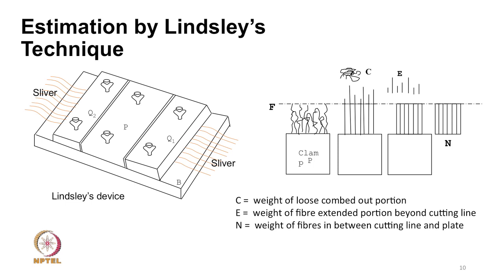Now, we will use a comb and we will start combing this part repeatedly. While combing, we have to be a little careful so that the fibers do not break. So, we comb them gently and repeatedly. After some time, we find that most of the fibers will be straightened out like this, and the fibers which are within this zone from here to there, but are not held by the clamp, will all be removed.